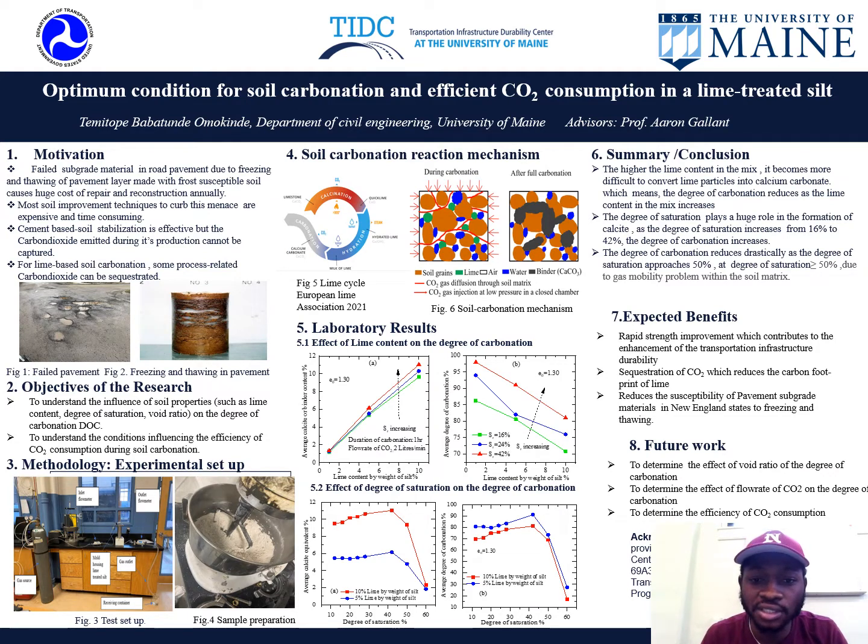The expected benefit is, one, it helps in rapid strength improvement, and also lime-based soil carbonation is a means to capture CO2, which is very, very good for the environment. It's a means to reduce the carbon footprint of lime, which is very good research for us. And also for the future work, I will determine the effect of void ratio on the degree of carbonation. I will determine the effect of flow rate on the degree of carbonation, and also I will be determining the efficiency of CO2 consumption.